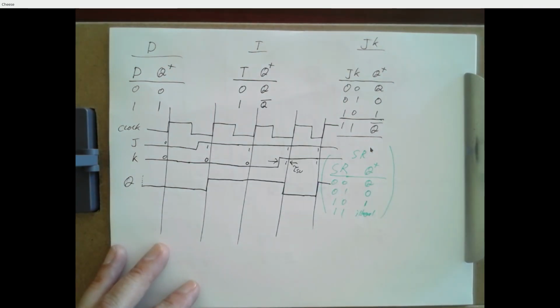And we're not allowed to change it until a certain amount after the clock ticks. That's the hold time, so tau H. Now suppose you were actually building this circuit. You were actually going to use this to make a soda machine, right? And you've got to choose how fast is my clock going to run.